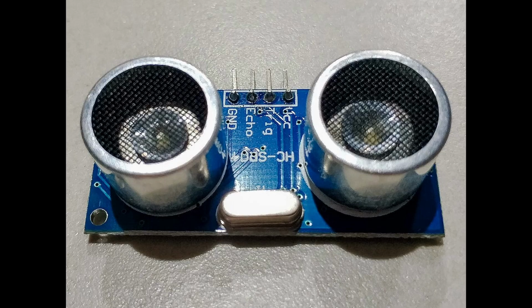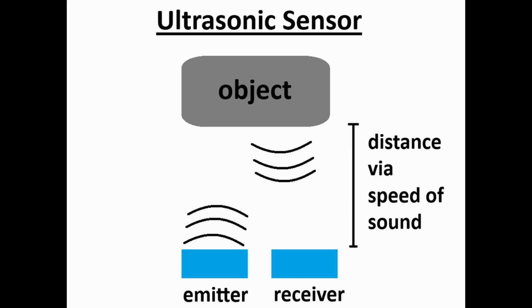Alternatively, we can measure distances using ultrasonic sensors. This device produces an ultrasonic sound pulse that reflects back from a target to a detector. The measurement range varies from a few centimeters up to about 10 meters or so. The time between the pulse emission and its detection can be used, knowing the speed of sound, to calculate the total distance traversed.